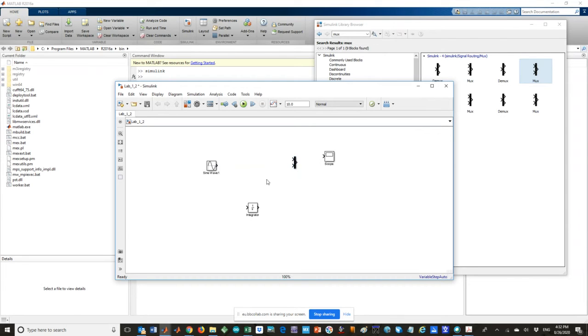Okay, now to collect those signals, look, in the new versions, they show a blue line. If I release my mouse, it will be here, and I'll just click on it. This is a connect, or you can click here with this plus pointer and drag and drop here. This is how you can connect or wire your circuit. This one, I'll bring that sine wave to this integrator.